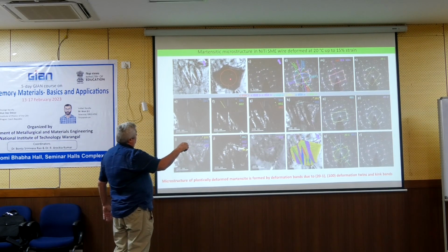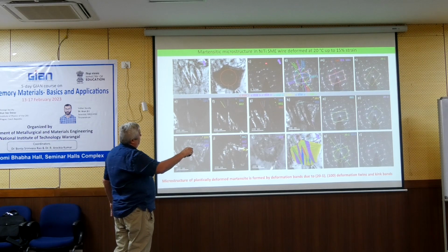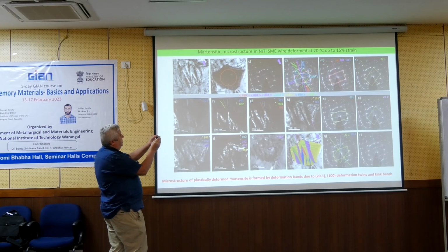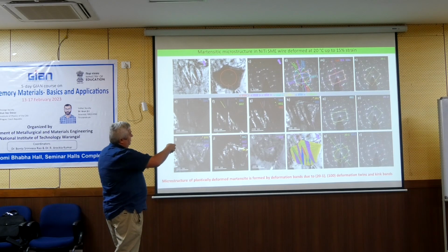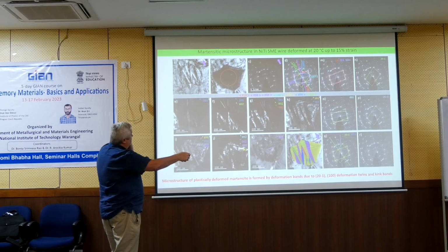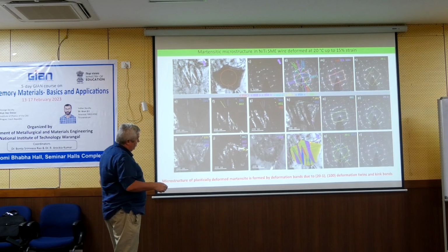So these are the diffraction patterns. All of them are in the 010 direction, but rotated, differently misoriented. To analyze this, we have something like six Martensite lattices differently oriented. And because this is a jungle and no one can understand it, I put here a few pictures which concern different kinds of lattices.